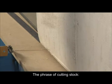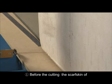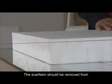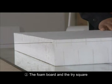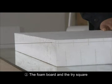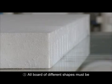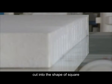The phase of the cutting stock. 1. Before the cutting, the scarf skin of the foam board should be removed. The scarf skin should be removed from the bottom or adjacent side. 2. The foam board and the tri-square should be mutually perpendicular. 3. All boards of different shapes must be cut into the shape of a square.